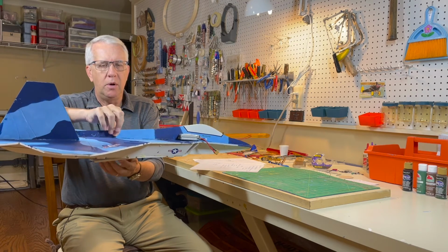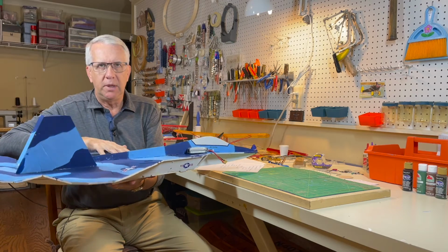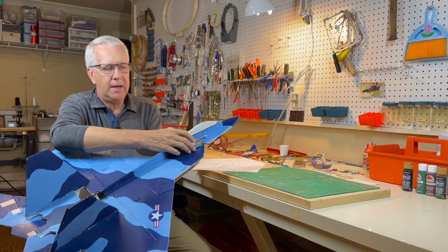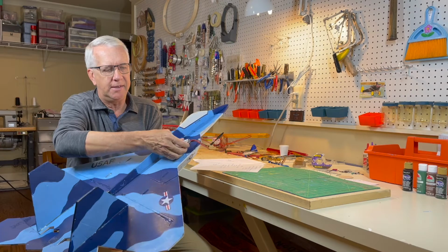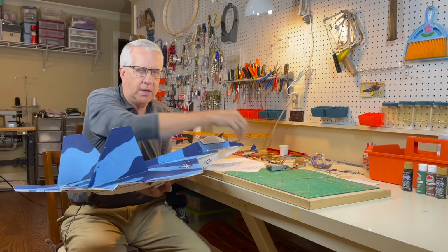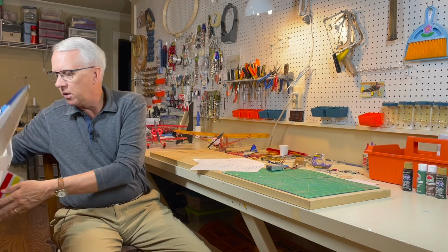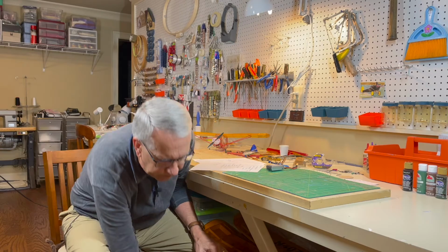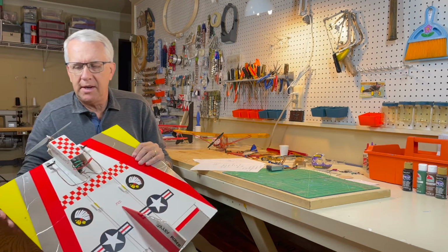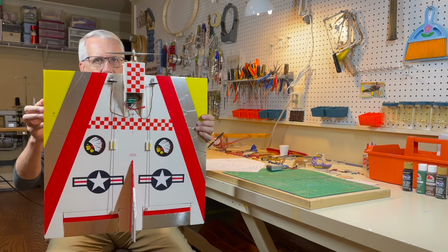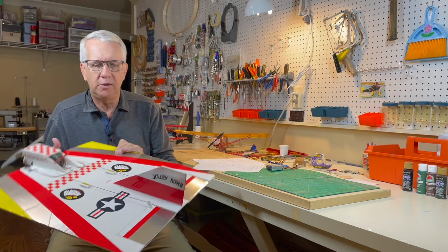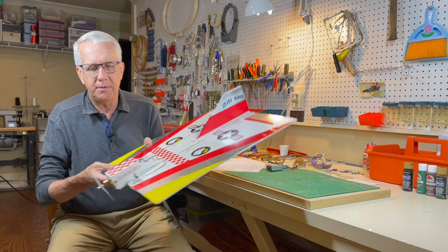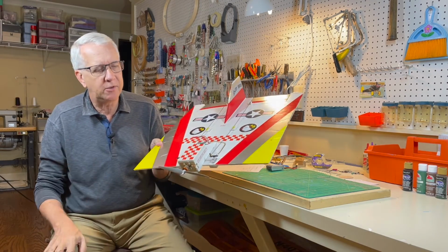So the important point is, as you're building from plans or designing an airplane, you may have to think early on in the design stage where you're going to locate something heavy like the battery, the motor, etc., to ensure that the airplane balances out. A good example of this is my design of the square flyer. So this is foam board. It's 20 inches square with elevons. Again, a link in the description.